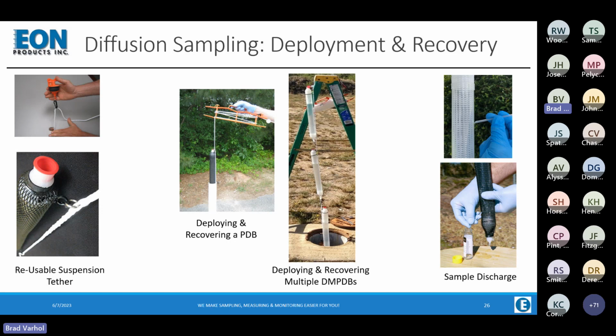And the discharge of the samplers, the preferred method. All of us have either been kids or have kids, so we've used a juice box. I like to refer to the discharge straw as a juice box straw. We puncture the membrane, and that provides us with a laminar flow into our sample bottle that has minimum air exposure.